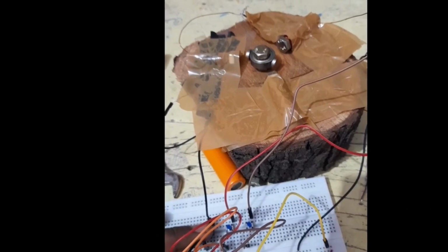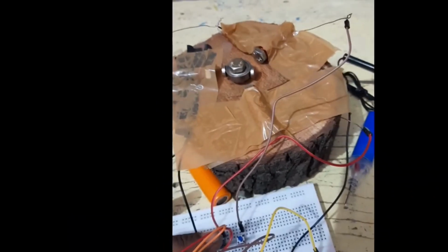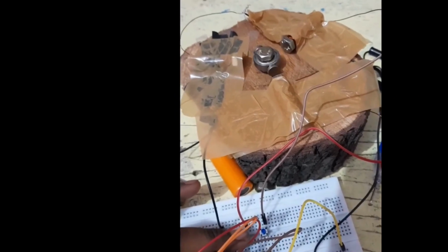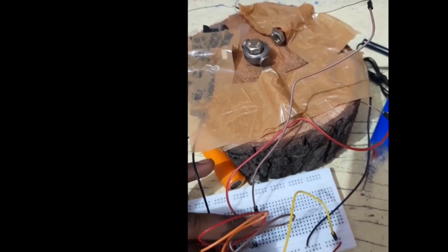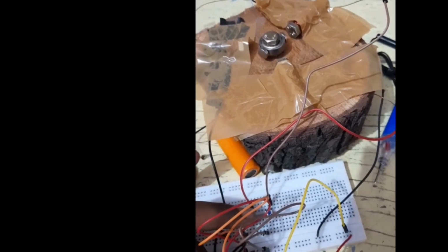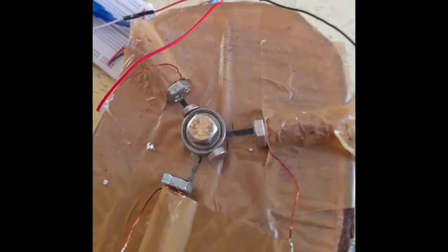You can see when I press the switch, the rotor is attracted to the coil, and similarly when I push another switch, it rotates to the respective coil. In this circuit, the coils are 120 degrees apart from each other to create a balanced supply system that creates a steady torque in a three-phase induction motor. And the magnet is close to the coil because field strength decreases when the distance between coil and magnet increases.